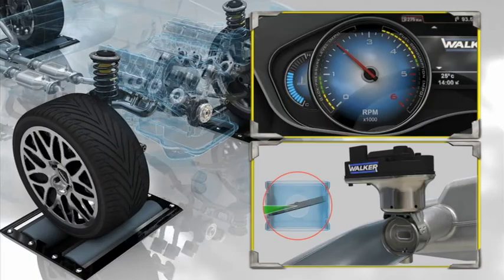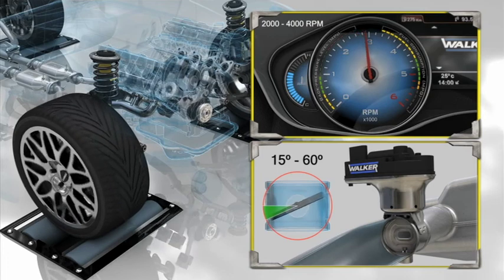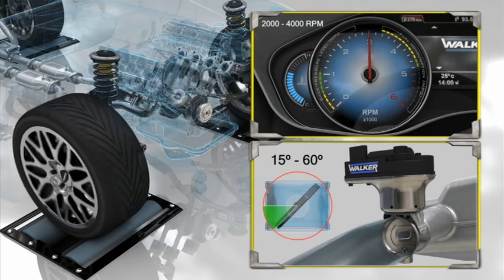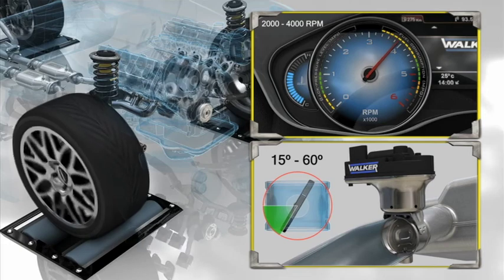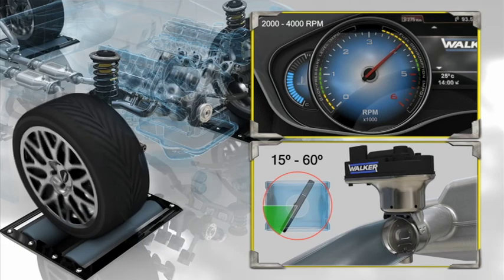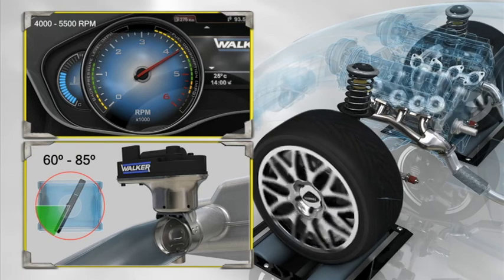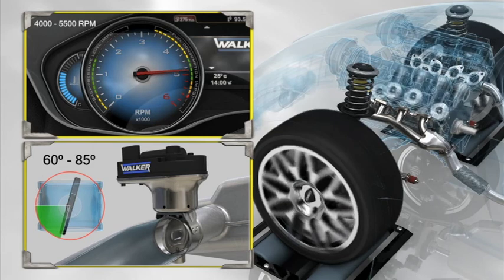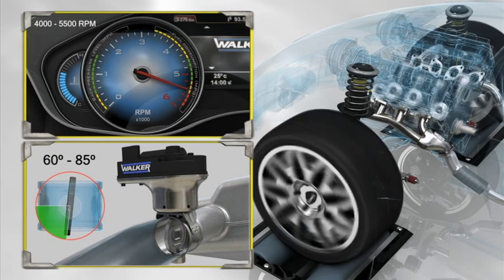When the vehicle is running, the valve opens or closes depending on the engine's operating conditions. The disconnection of cylinders, subsequent reconnection, increased speed, etc. will be the conditions which determine how much the valve opens. When the vehicle is operating at increased load conditions, i.e. at high speed and on all cylinders, the flow of the exhaust gases will be maximized, so the valve is completely open to enable the gases to pass with the minimum back pressure.